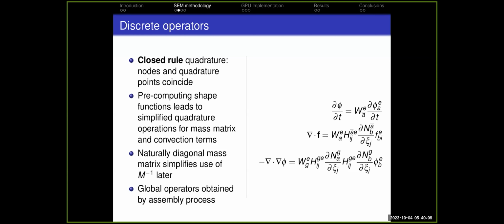What happens is that on the mass matrix operator and on the divergence operator, with the GLL quadrature, what we are essentially doing is coinciding the quadrature node with the element node. So the shape functions evaluated there are essentially 1 or 0. We observed that before implementing, so what we actually implement are operations that already take this into account.